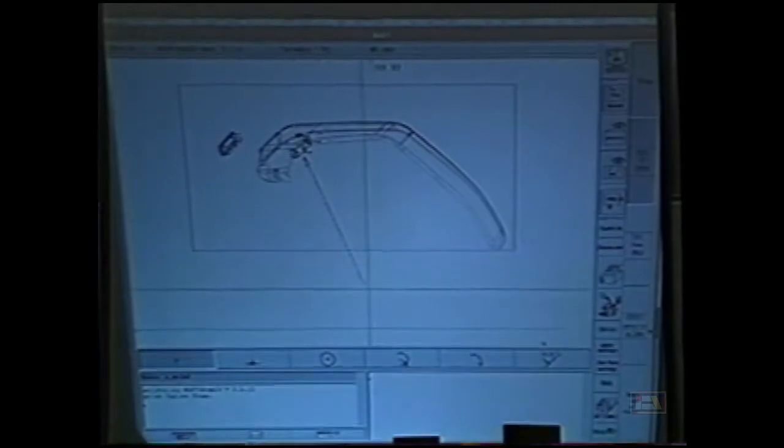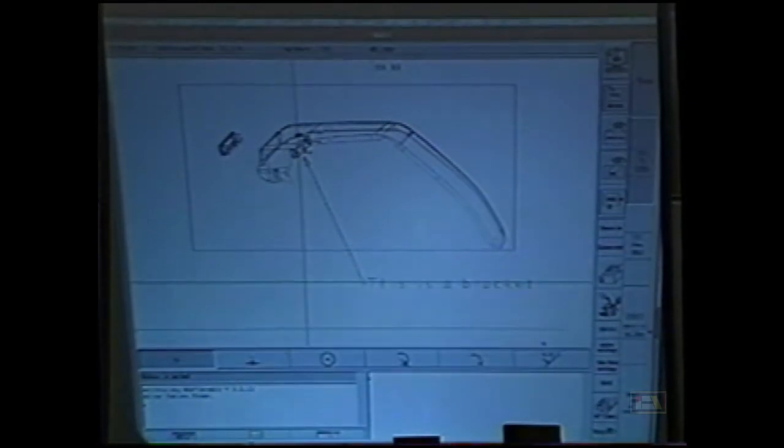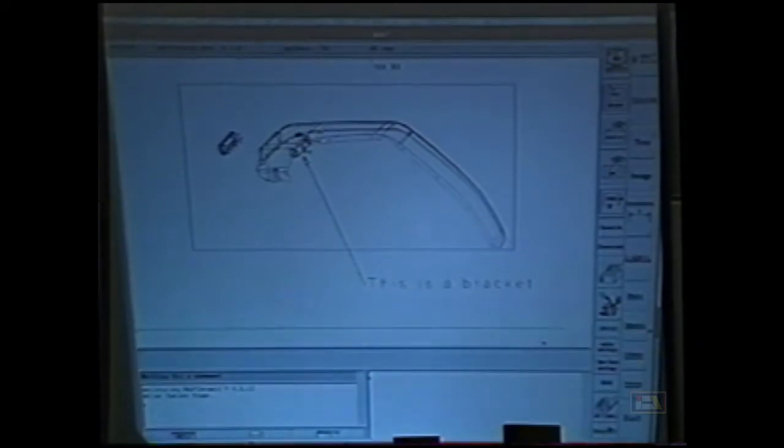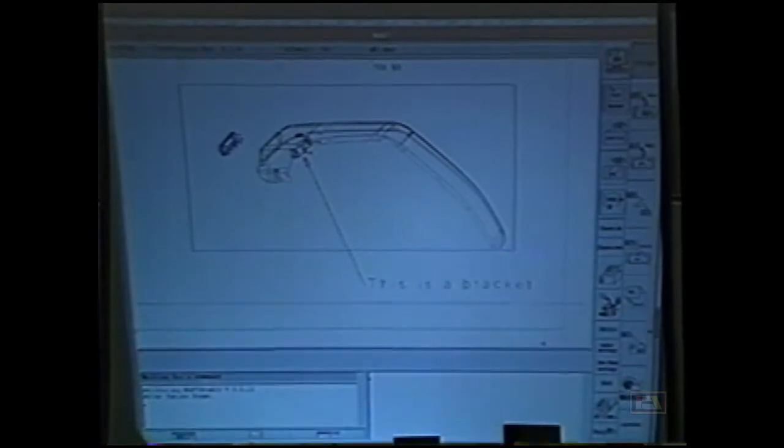So like any other graphic packages, you can change the font and the settings of the line. We also have a box around the image, and we can change that. For example, we can go to image, use options, say it's in cadre, I assume means box in French. Not everything's translated yet. And then go to change and click. There you go. You don't have the box anymore. So you can make a lot of modifications. Took off the arrow. What happened to the arrow? But you can bring it back.